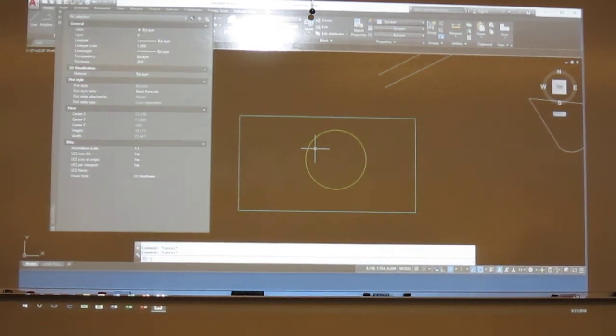Okay, well, if you're using Dynamics, and it looks like there was 3 of you in there, that's a useful little tool for you. So you can do the distance and angle without typing DI or even using the properties dialog box. I don't like that. I don't like having it right there.